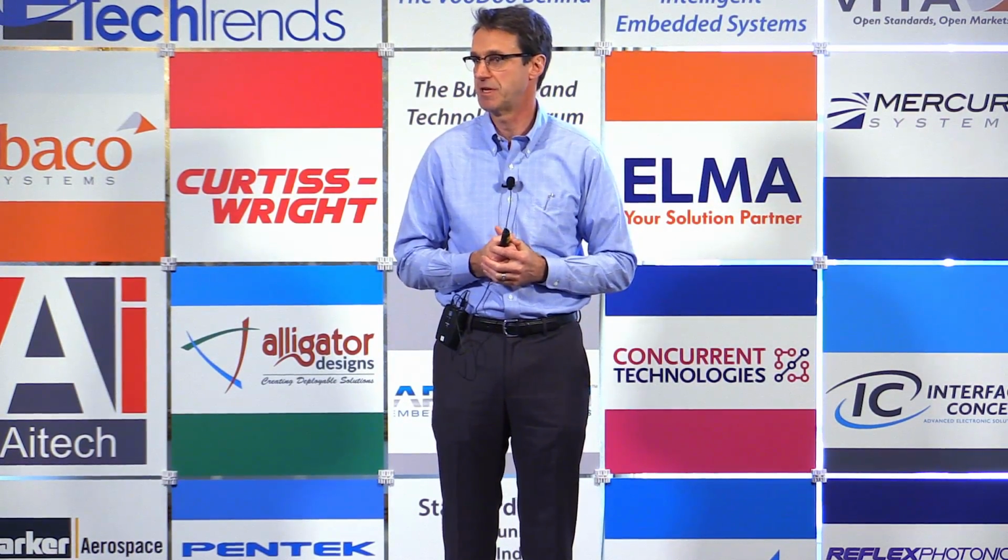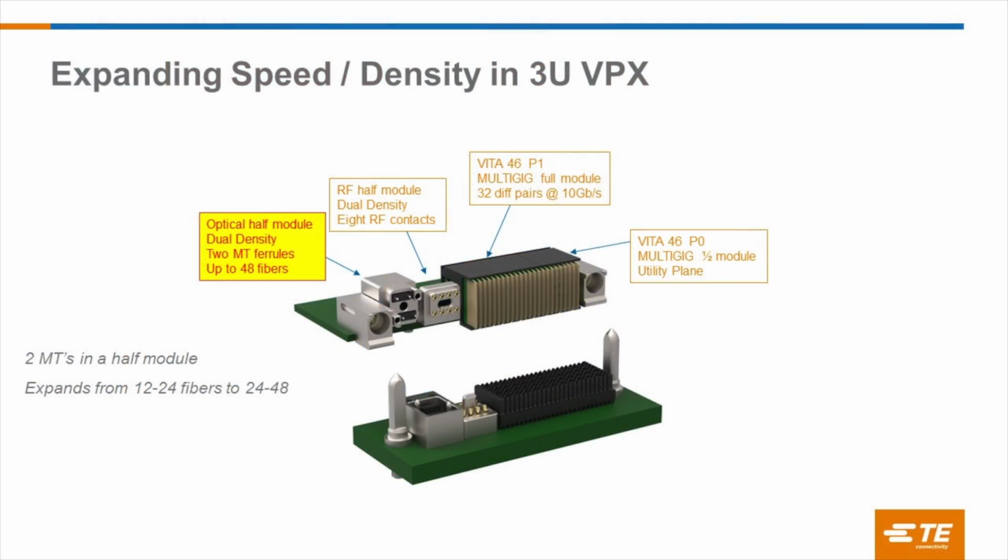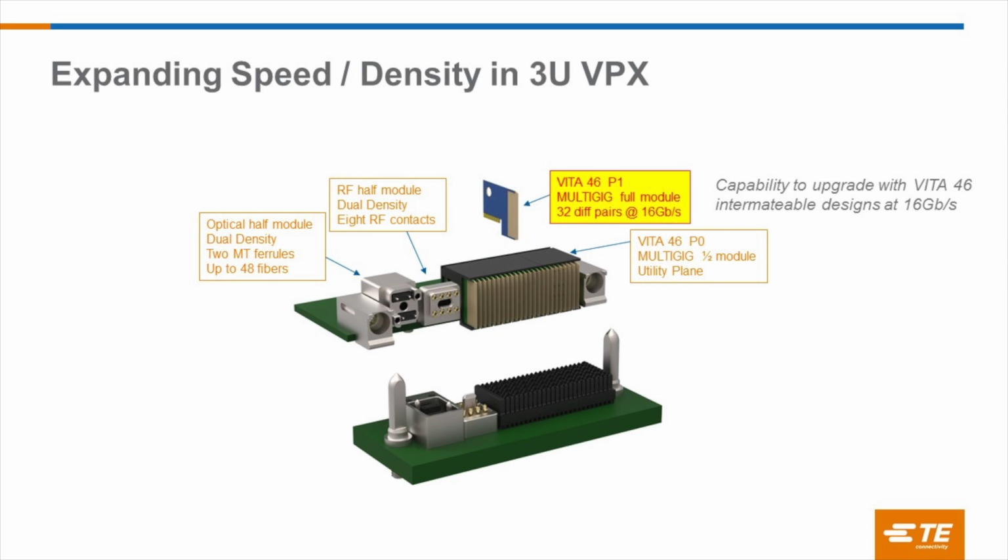And this is really just a view showing a 0.8-inch pitch application. With a 1-inch pitch, we can get 12 contacts in. So you remember that view that we were looking at, 12 contacts using up more than half the real estate. We can do that in half a module. For the optical module, we can double the density by resizing the guide pins and repositioning the MTs. We can get 2 MTs within a half module space. Again, we're doubling the density and not taking up any more space on the 3U card.